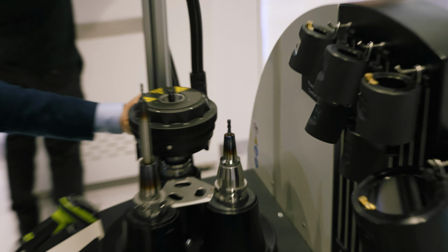It checks automatically how much heat is induced. I take out the old tool, put in the new tool within seconds. Same rigidity, same accuracy, same run out, same balance, and I cool it down. And this is digitization, a start into digitization as well. You don't need to remember torques, the cleanliness is much easier, the consistency is easier, no matter if it's done in first shift, second shift, third shift, always perfect rigidity, perfect run out.